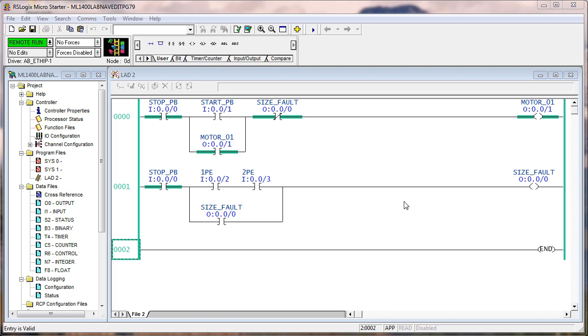And let's say a carton comes along. First thing that's going to happen is if the conveyor is stopped, then the carton will come up against the leading edge or the entrance of the conveyor belt and just stop there. Then if you turn the conveyor on, the carton starts moving. It gets pulled on by friction, and the first thing it does is break 1 PE.